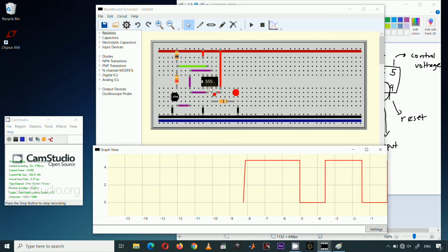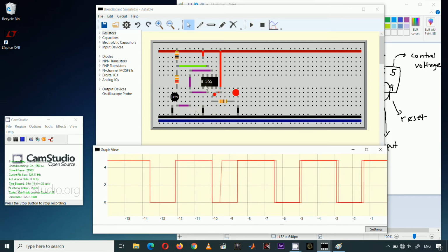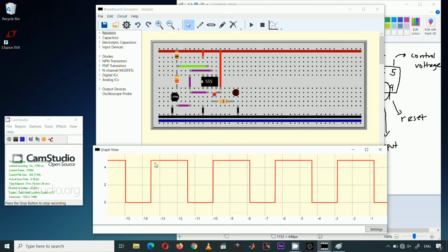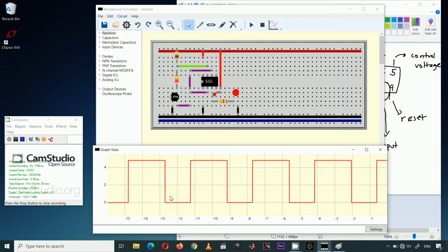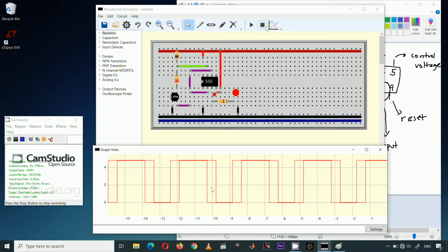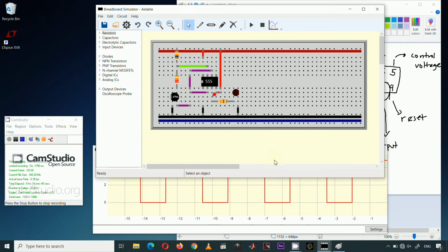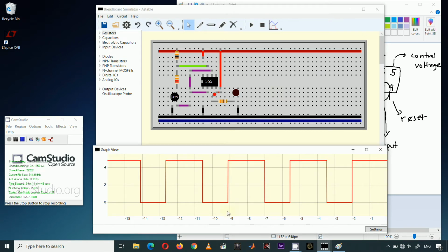So apparently, this initial voltage high output has something to do with the capacitor interacting with the 555 timer, but apparently the succeeding voltage high output is now consistent with each other. And let me pause it. So notice that the duration of the new voltage high output is 2 seconds because I edited the value of the capacitor and I doubled it. This change was reflected in the output of the 555 timer.